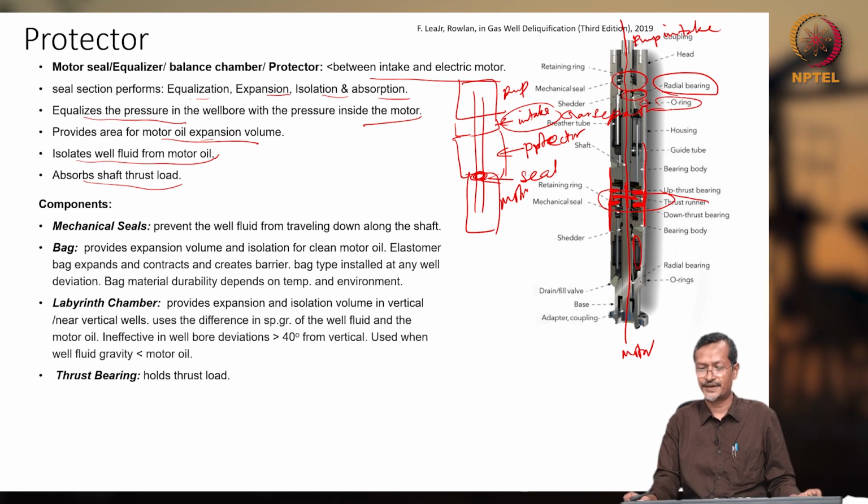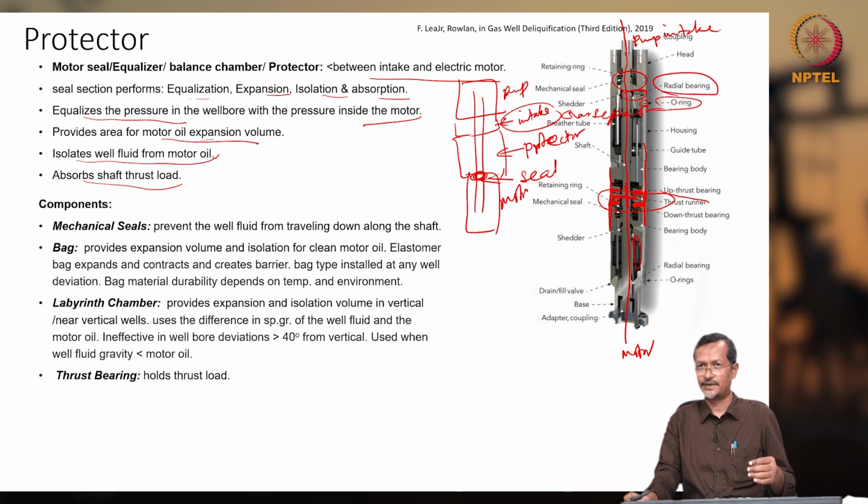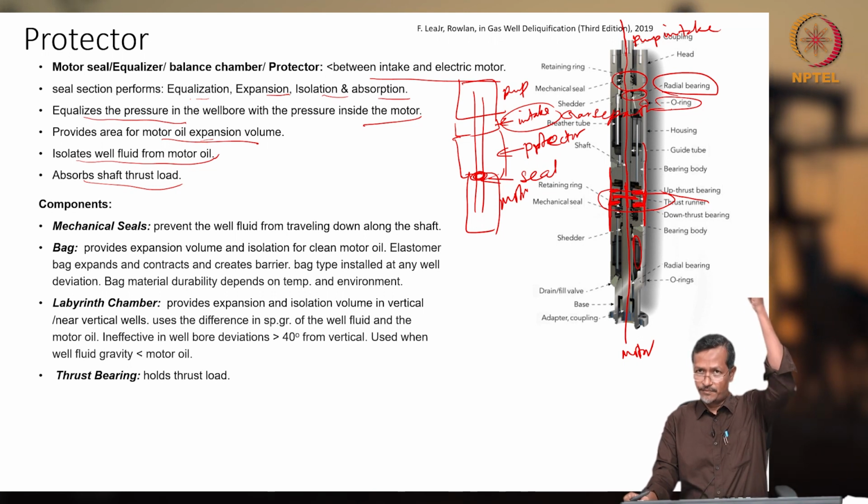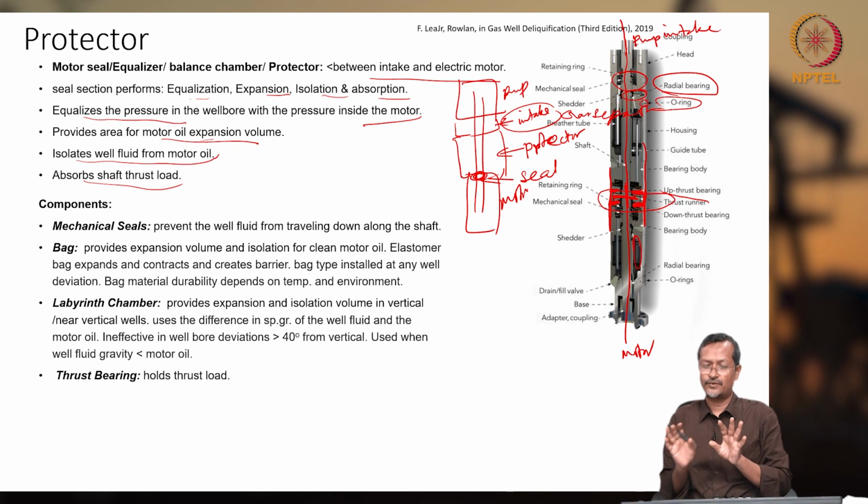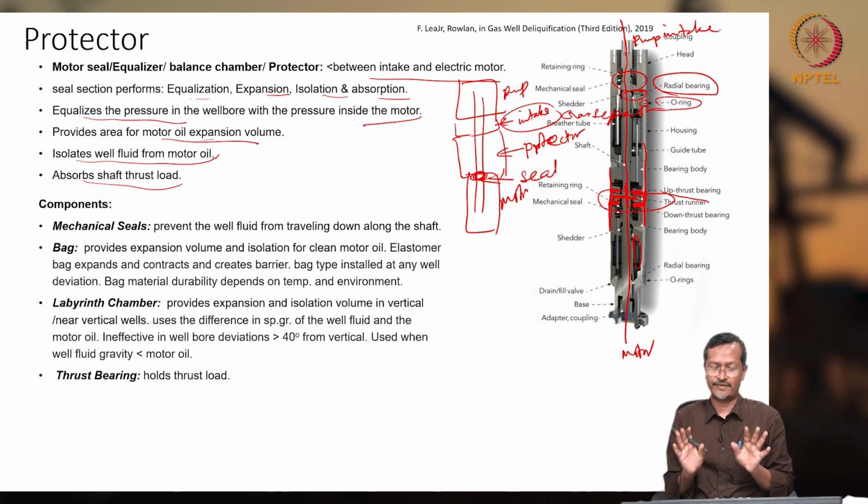If you are not putting this thrust bearing or radial bearing, there will be multiple issues. Because you do not want to transfer pump load to your motor; you want it to work peacefully, safely.